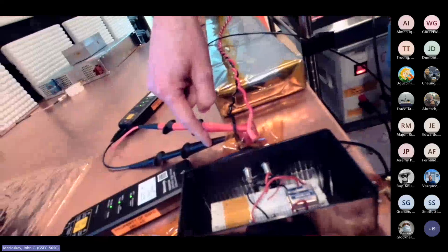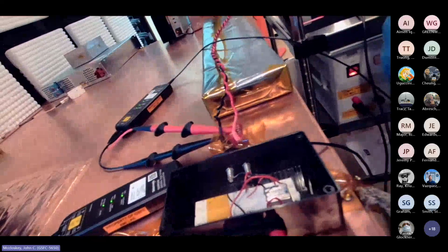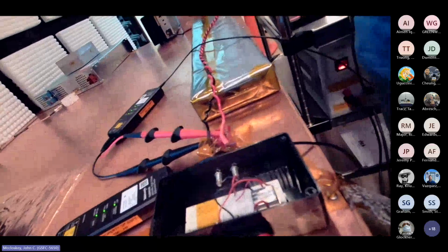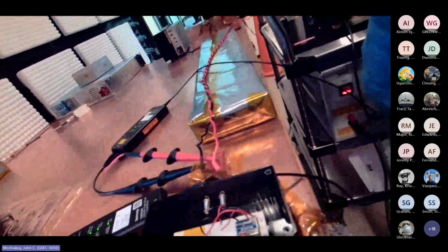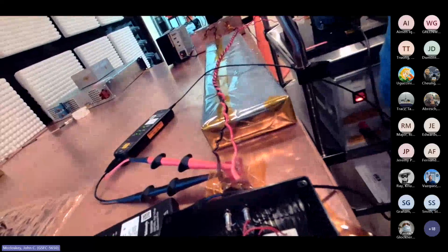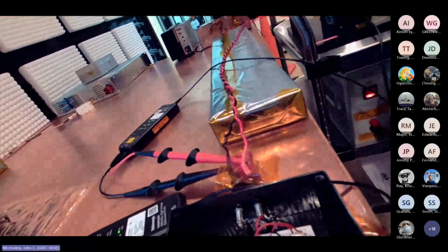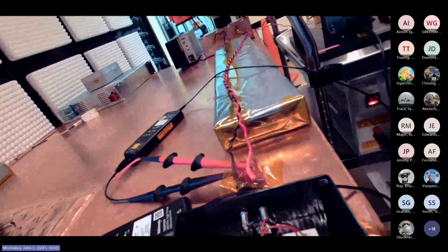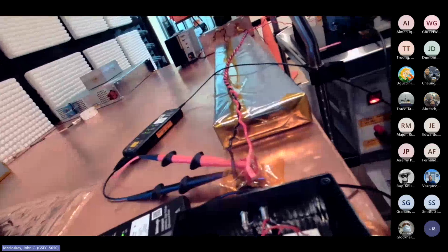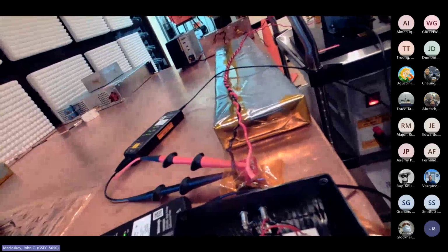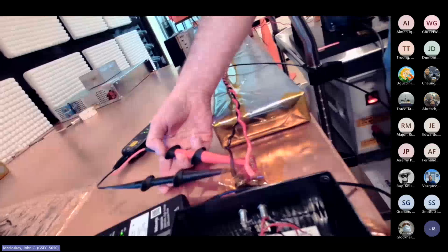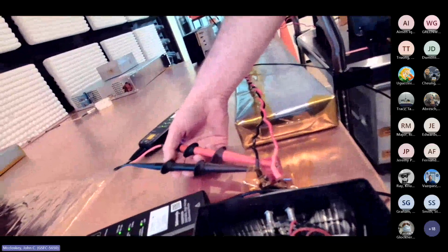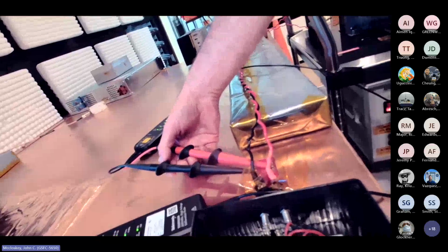so that you're not connecting the return lead of a standard scope probe, which is going to go to the scope chassis, which then ties to facility ground. In a lot of cases, you might be able to get away with that, but it's not a good habit to get into because that can affect your grounding, especially at the low frequencies, right? You're starting at 30 hertz, and you're going to go right through 60 hertz. It can definitely cause some 60 hertz ground loops that could cause some weird things to happen in your setup. So I can't emphasize enough that you really want to use a differential voltage probe as much as possible. They're not real cheap, but they're worth every penny if you invest in them, right?